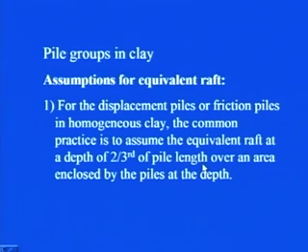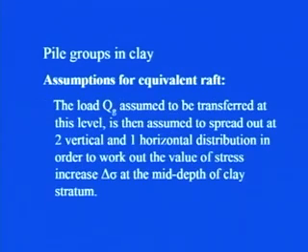Whatever is the area enclosed by all the piles, we place the raft of the equivalent area at 2/3 of the length of the pile. The load Qg is assumed to be transferred at this particular level and is then assumed to spread out at 2 vertical and 1 horizontal distribution in order to work out the value of stress increase, delta sigma, at the mid depth of the clay stratum.